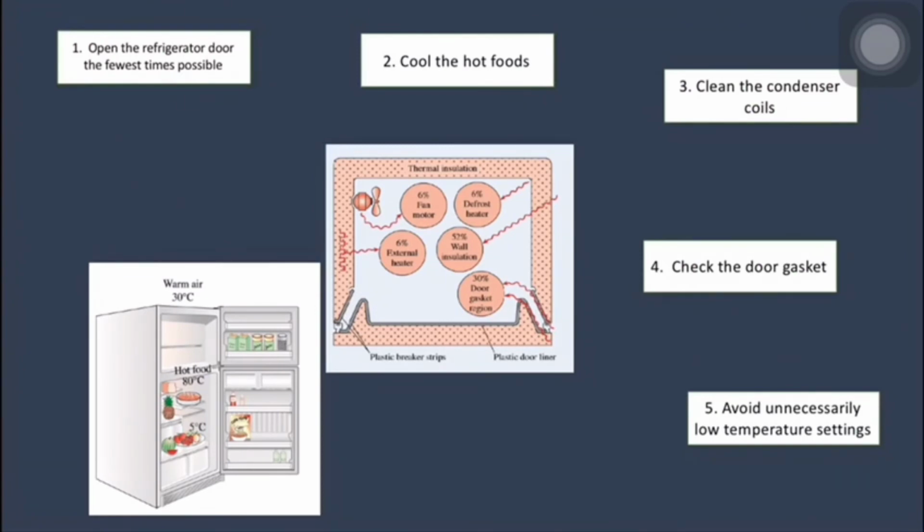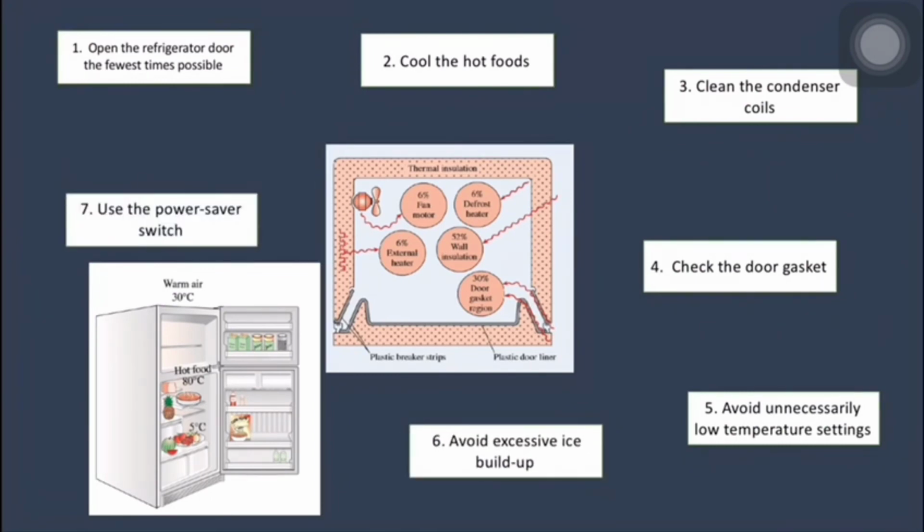Sixth, avoid excessive ice build-up on the interior surface of the evaporator. Seventh, use the power saver switch that controls the heat coils and prevents condensation on the outside surface in a humid environment. Eighth, do not block the airflow passage to and from the condenser coils of the refrigerator.